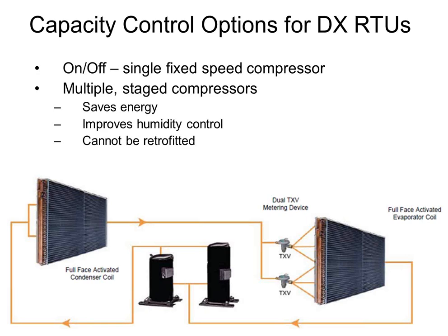In fact, the only time I would ever tell you to use a single stage unit is if you've got a big open area like a Walmart or whatever, and you want to use a bunch of rooftops and let them stage with each other. So the system still is sort of staged, even though the individual units have one. Maybe you can get away with it there, or in a big warehouse or something like that. But anytime it's one rooftop going to one particular area, I think you want to try to get 2 stages if at all possible.